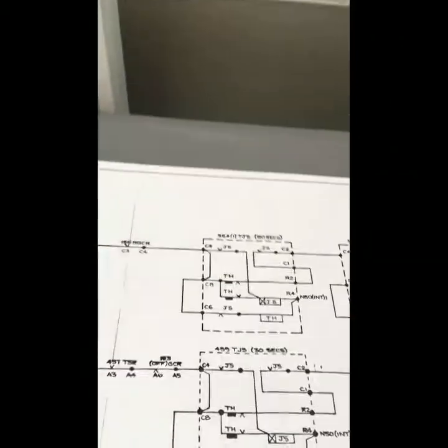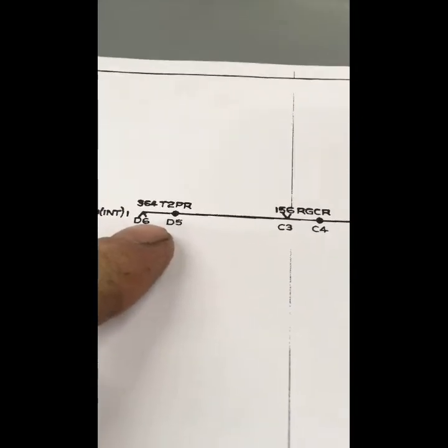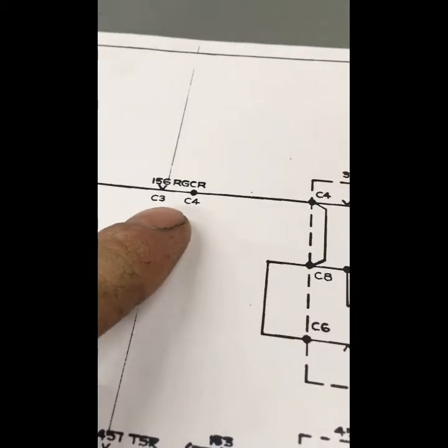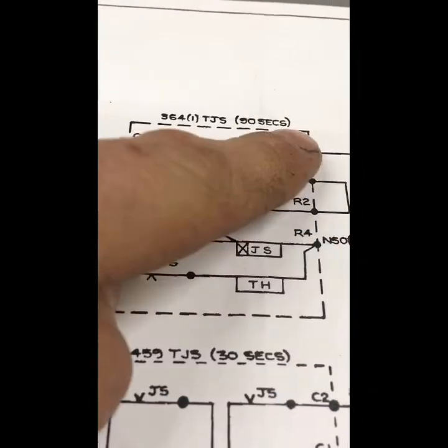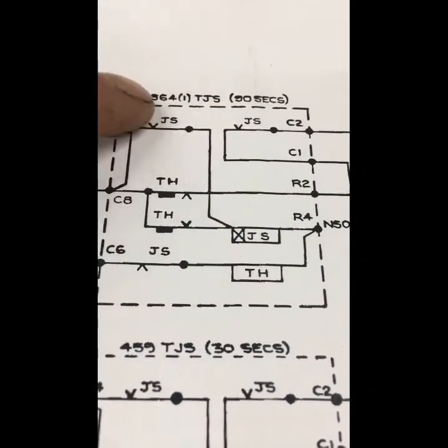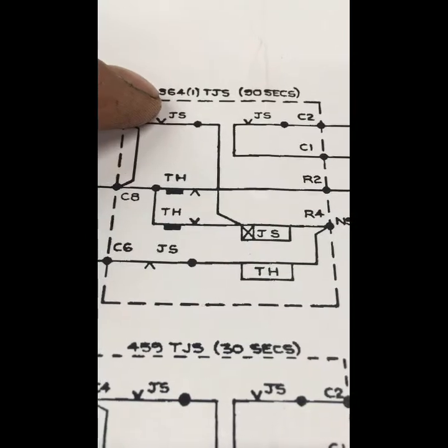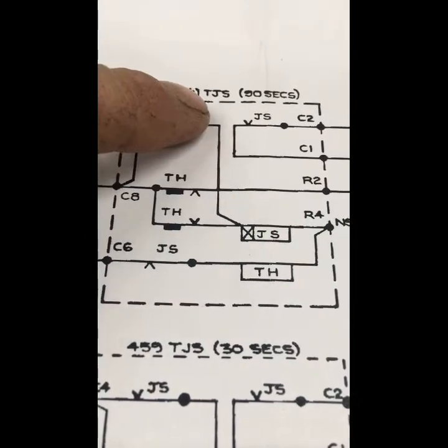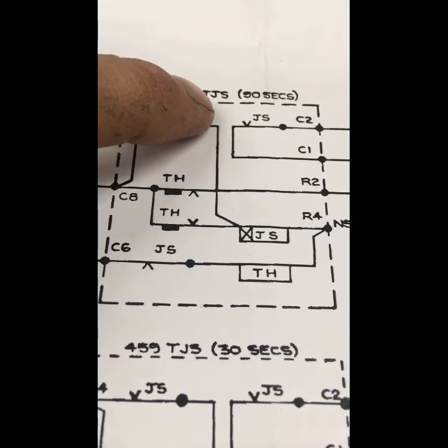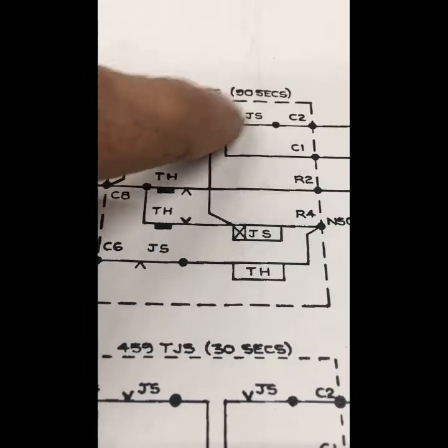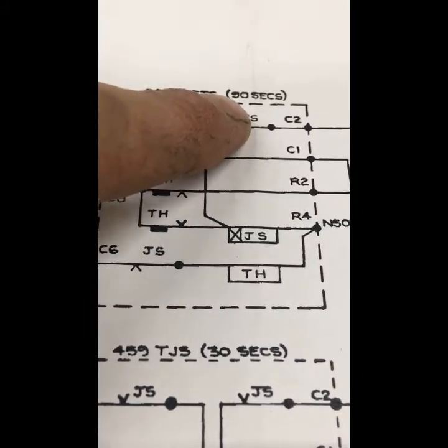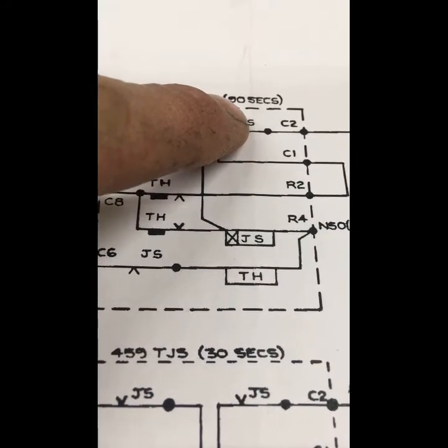Here we have one of our timer circuits for our timer relays, and if we look across here, we have our positive feeds to the left, with our track down and our signal red. It then initiates the timing sequence. Now we'll follow this through. Everything inside the dotted lines is inside that timer relay. It tells us the number of the signal or points, its route, time, stick circuit, and it tells us the time. So it's a track timer stick, and it's set at 90 seconds.